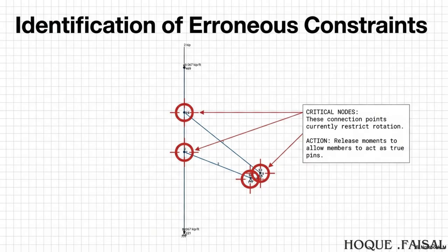Then the 81 mile per hour wind hits. The real joints, which are pinned, not fixed, rotate freely just like they're supposed to. The beam deflects way, way more than 0.077 inches. The geometry changes, the system becomes unstable. And it falls down. Potentially.